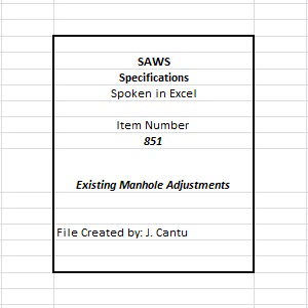4. Manhole rings and covers shall be in conformance with specification item number 852, sanitary sewer manholes. 5. Internal liner for use in conjunction with HDPE throat rings, refer to specification item number 852, sanitary sewer manholes, UV stabilized polyethylene for the purpose of providing an infiltration/inflow, I/I, barrier.